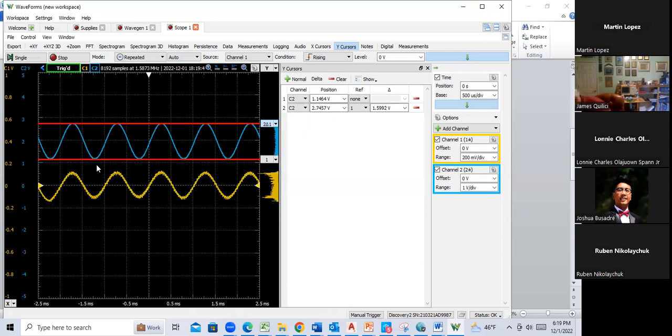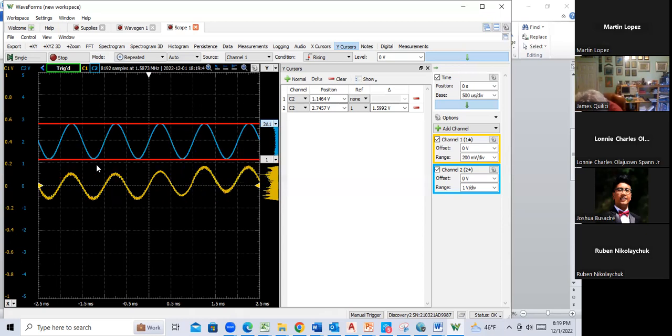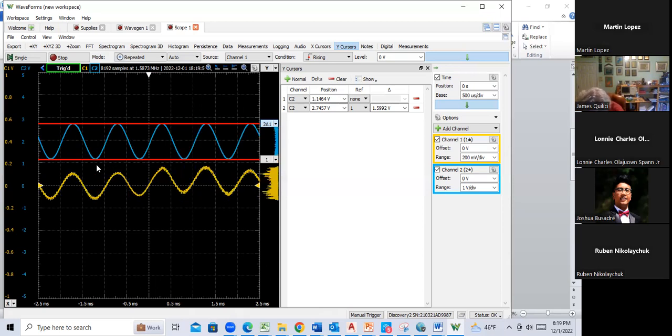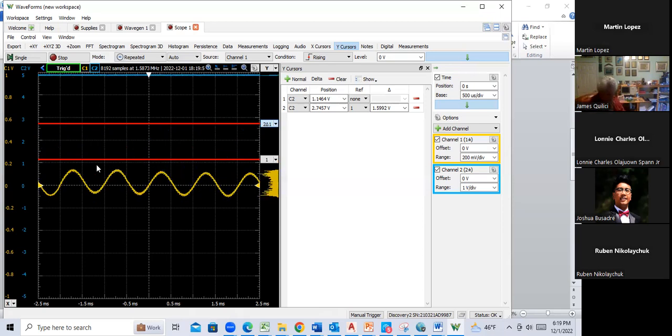So right now in my emitter, I think I changed that to red, brown. What did I change that to? Oh, that's 150. Yeah, that's red, brown, green, brown, 150. So I'm going to switch that now to 120 and see if that does it too for me. So I need brown, red.